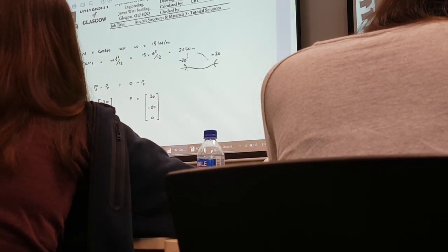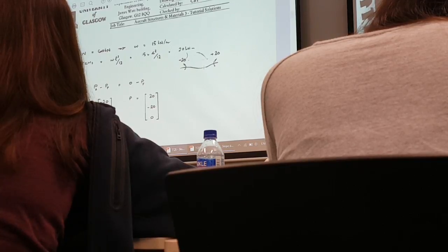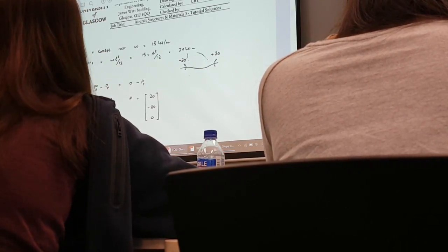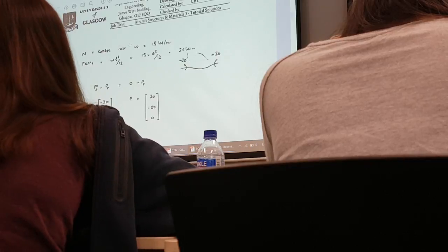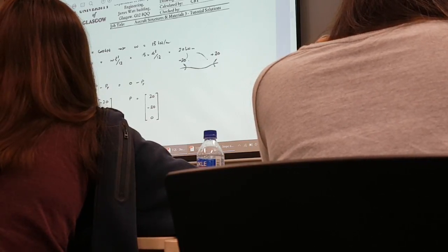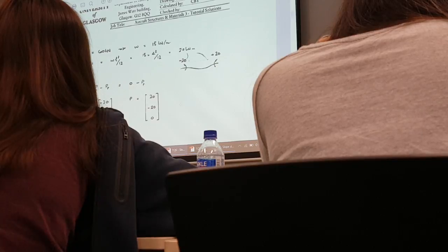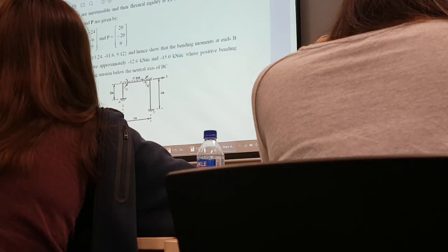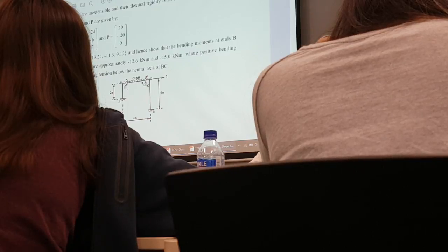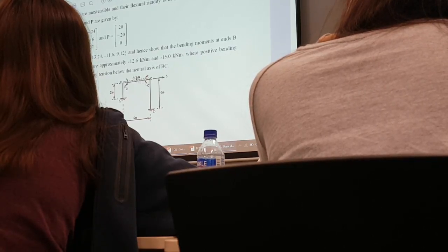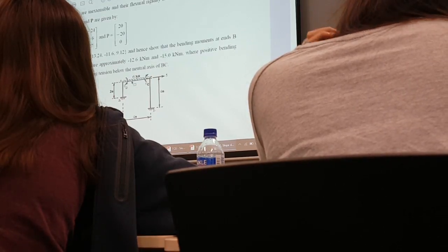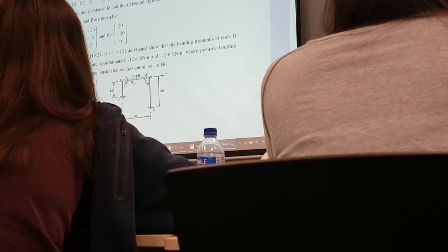And how do you calculate the fixed end moment? Of course, based on a formula you need to know: it's wL squared divided by 12. Why do you need to find w? Because if you look at the question, it states the uniformly distributed load. Let me go back to the question again. This wavy form is the symbol for uniformly distributed load. But this value given, 60 kilonewton, is this a small w or a capital W? So you need to take note.